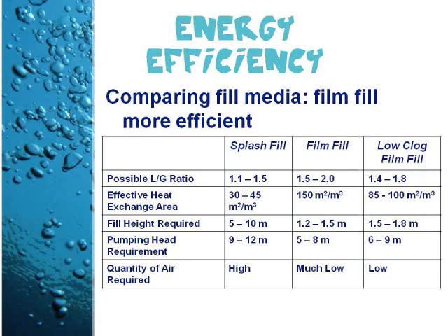From the table, we can see the different parameters for the different fill media. The liquid to gas ratio, heat exchange, pumping costs, which all impact on energy use. The table compares these parameters between the three fill types. From the table, we can see that film fill media is more efficient than the two.